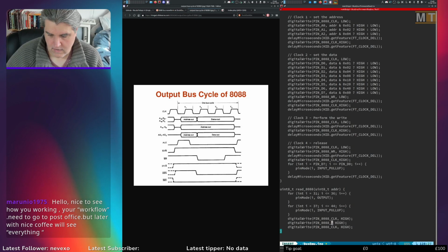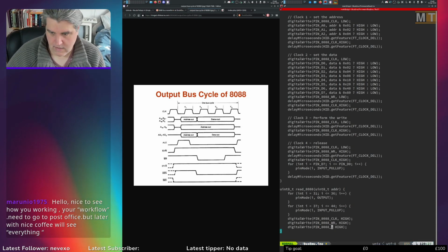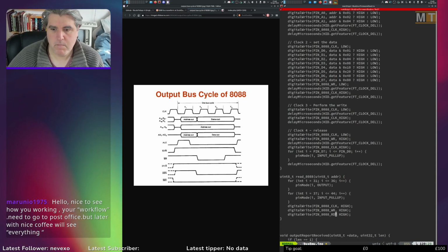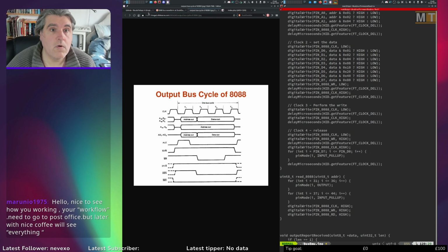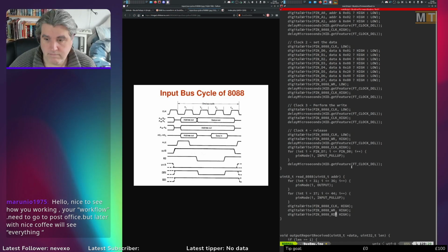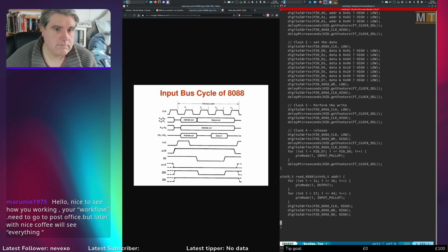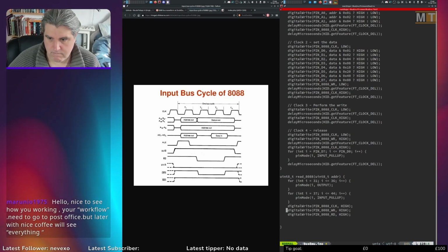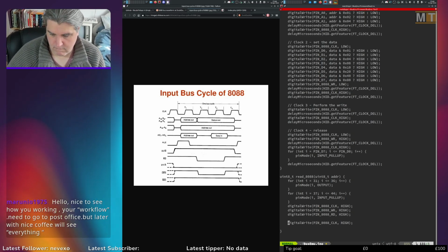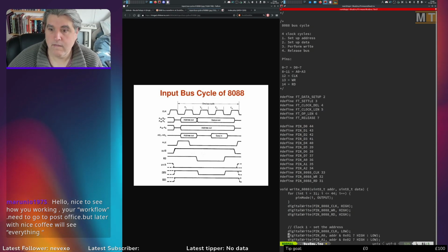So we have write and read and clock all start high. Okay, then we have for the read cycle. Clock goes low, address gets set, clock goes high. Let's copy this.